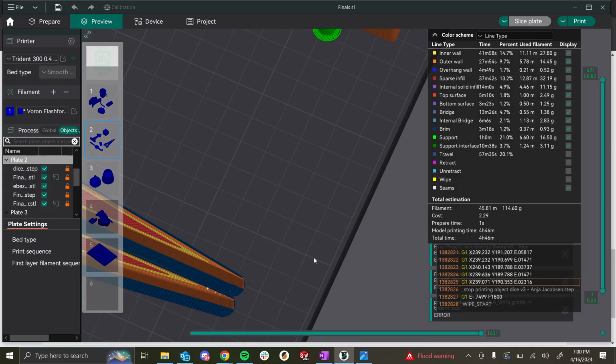You can make modifications to the object with STL. Okay, so different colors is a very good question. At this point, my printer only prints one color at a time. The trick to quote unquote multicolor printing is I can pause the print, change the color and then continue it. But when you have really detailed colored models where it needs more than one color on the same layer, that's when you start getting into multi-material unit territory. I haven't built it yet, but I'm building an MMU for my printer, so it'll allow me to print 8 colors at the same time or more.